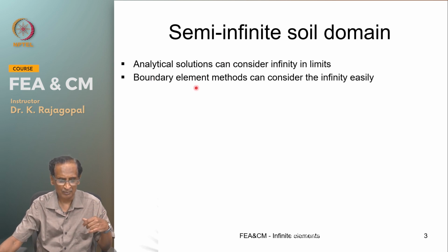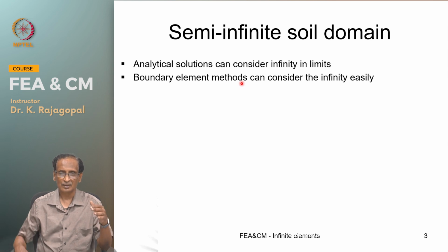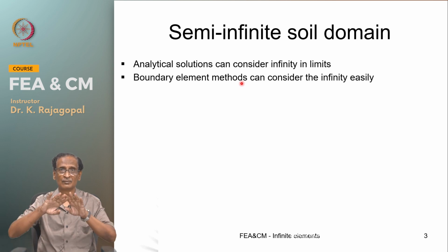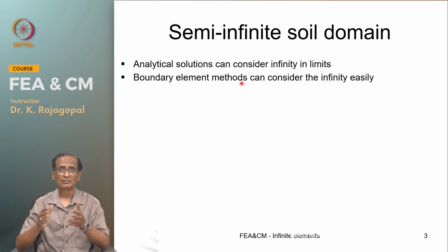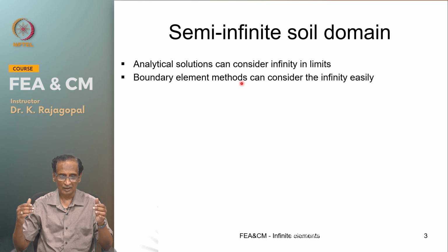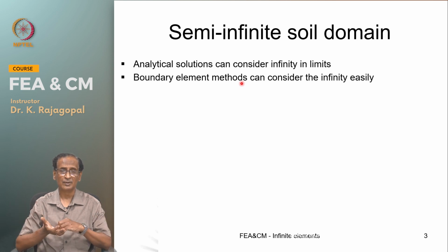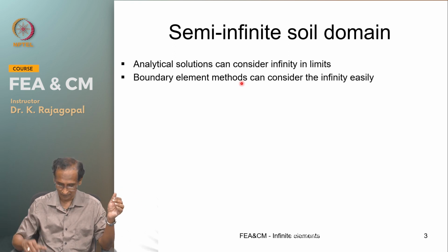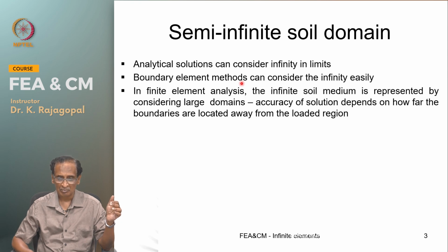And the boundary element method is not similar to finite element, but it's another numerical method where we consider the boundary and we can represent either the outside of the boundary or inside of the boundary, because if you say outside of your boundary everything up to infinity, that is automatically considered in the analysis.